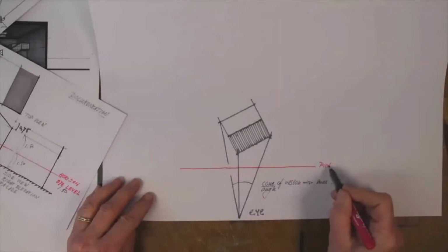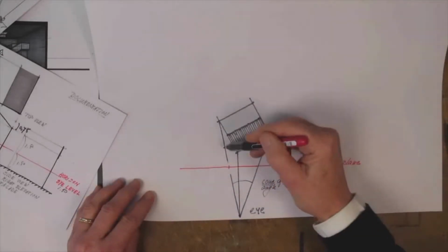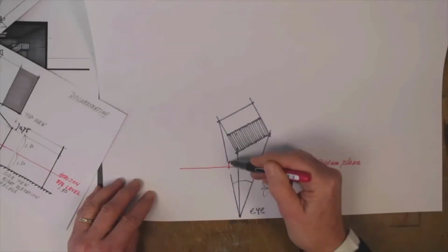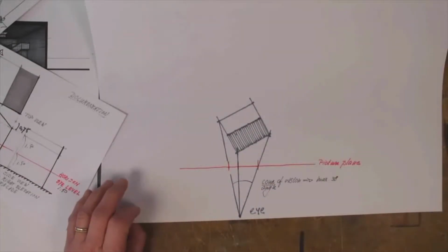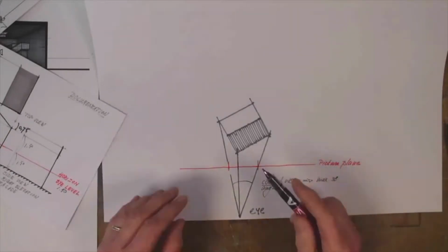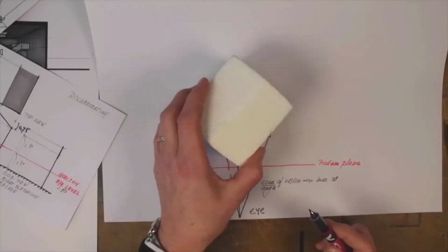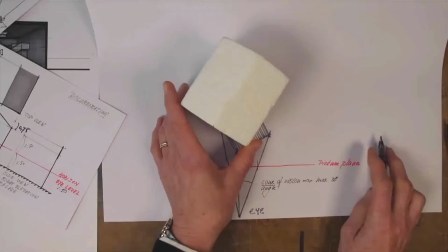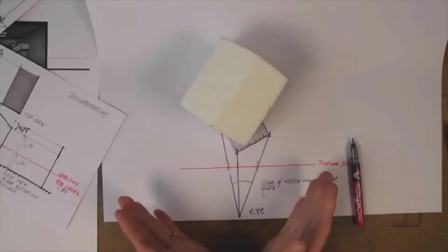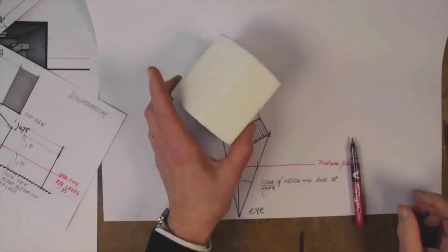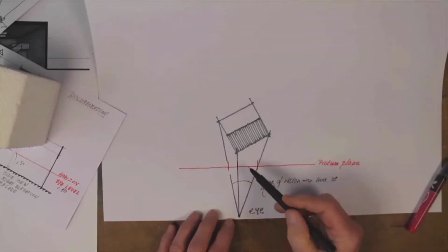You put the picture plane perpendicular on the line, which meets the first rib of the house. Usually the picture plane is in between you and the object, like could be seen in the model. In that case, you get a small drawing. The vanishing points can be placed on the picture plane too.